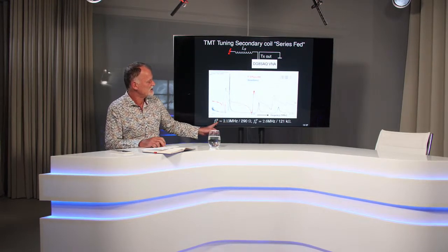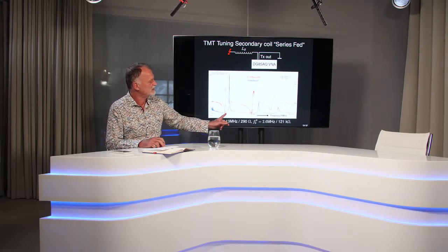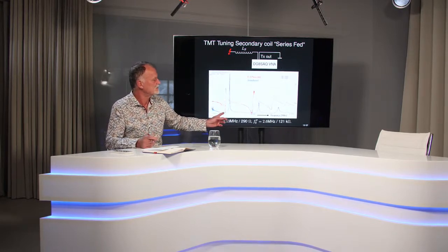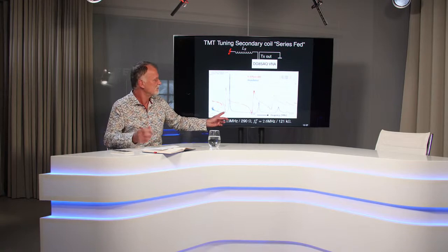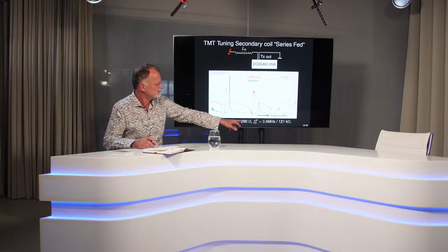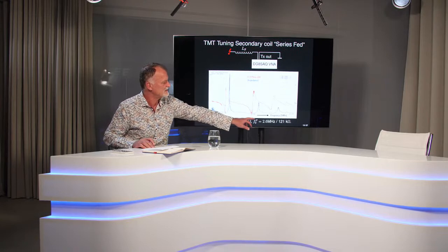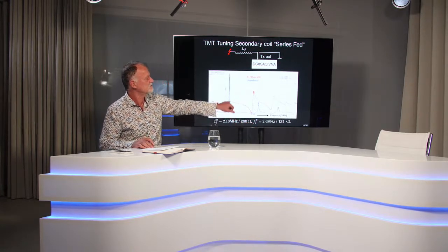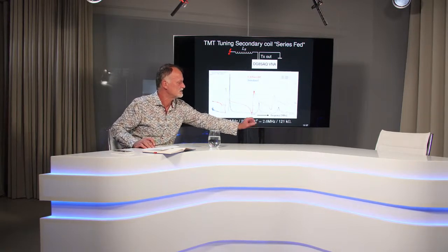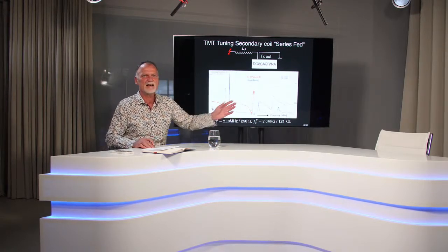At 2.13 megahertz we see the minimum impedance and the full phase swing, which is characteristic of the serial resonance mode. Next to it is the parallel mode with very high impedance. The impedance jumps from 290 ohm to 121 kilo ohm, right? The frequency of this first parallel mode is 2.6 megahertz. Then you see a replication, and these are higher harmonics, right?